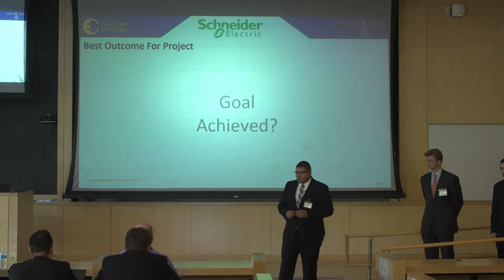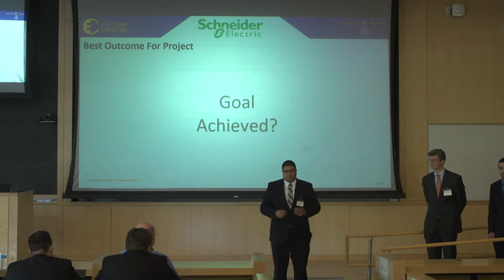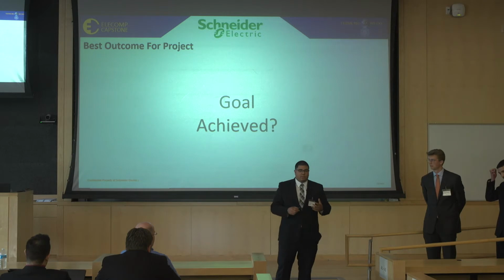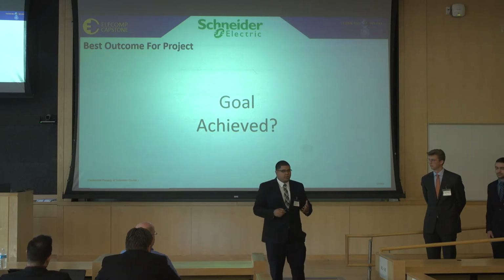So the big question is, did we achieve our goal? Unfortunately, we did not. Our best anticipated outcome was a full redesign of the circuit, of the system. However, we did redesign several different sub-circuits, as you just saw. The biggest one being the optocoupler-driven N-type MOSFET, which with correct implementation and a new bias DC supply can save a considerably larger amount of power than what is currently being implemented.